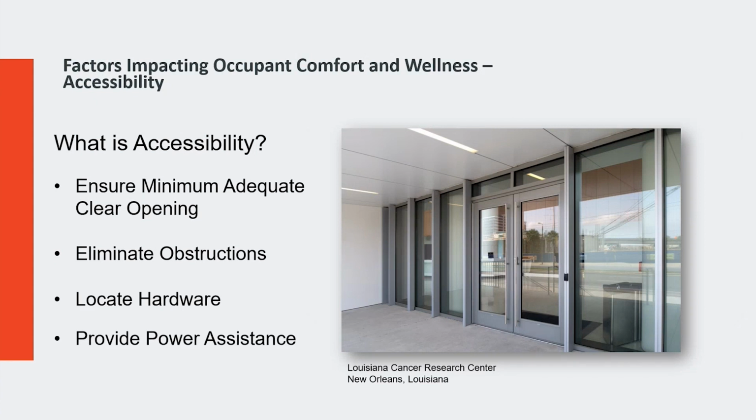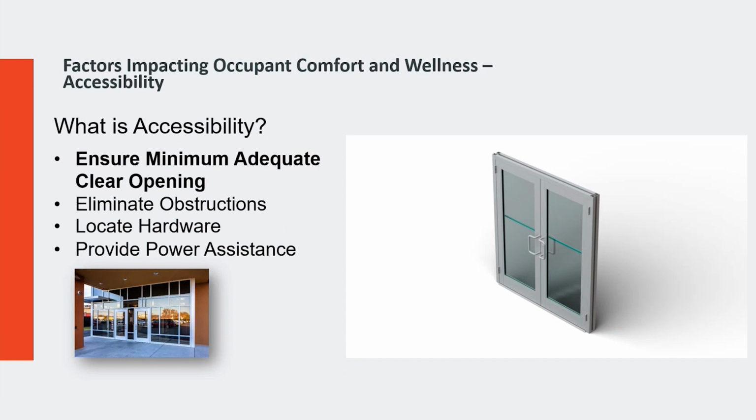Here's an entrance going into a hospital, and you can't see it well in this picture, but there is an automatic operator on the inside, and there are handicap push pads on either side of the doors on the interior and the exterior. So somebody approaching this entrance just needs to reach over and push the paddle button, and that's going to automatically open the door and hold it open long enough for someone to easily get through the entrance to the interior.